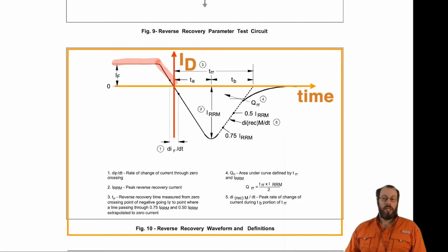But we are not reaching that 0 stage immediately, but first after the reverse recovery has taken place. The reverse recovery are charges which are stored in the PN junction, or also in the semiconductor metal junction for Schottky diodes, which need to flow in the reverse direction of what the diode just conducted.